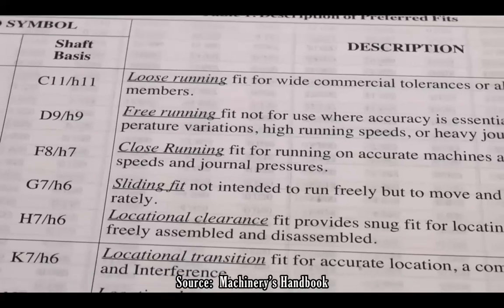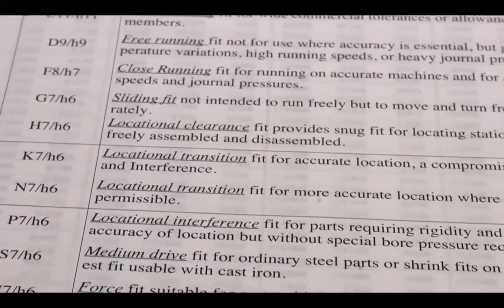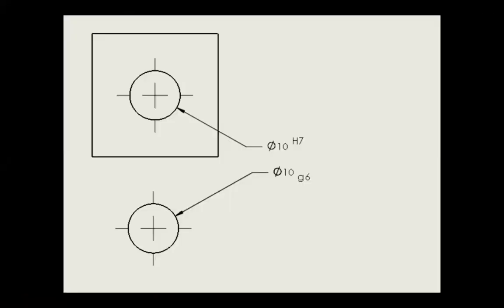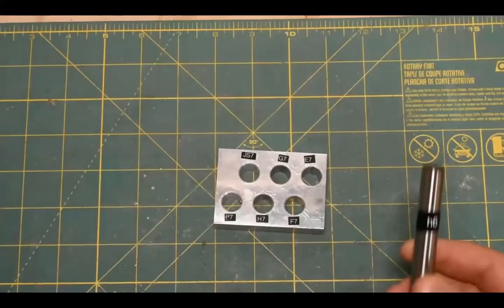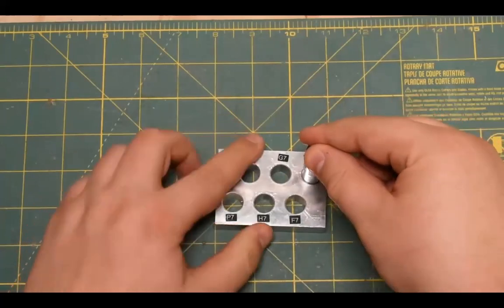So what does a fit look like in the ISO system? It's simply the two tolerance zones specified next to each other. An H7/G6 fit means, for example, the hole has an H7 tolerance and the shaft has a G6 tolerance. I've cut some holes in this piece of aluminum to show some examples of different fits. This is an undersized H6 tolerance dowel pin.